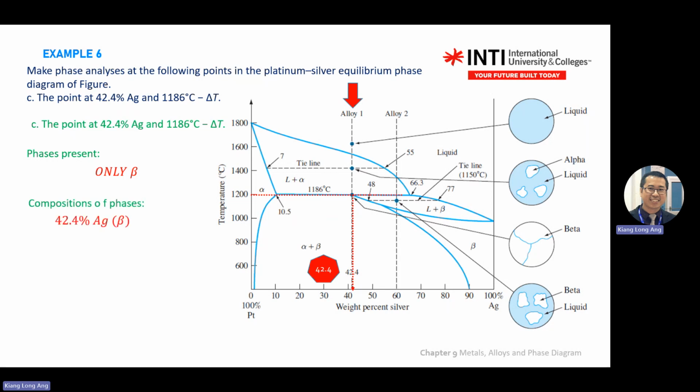Okay, so this one you straight away read it's 42.4% beta. So this one, highlight, and this one normally is the careless mistake when you see a very complicated line, for this PbAg graph. Amount 100% solid. Again, unit is percentage, wt percent, because you only have beta.